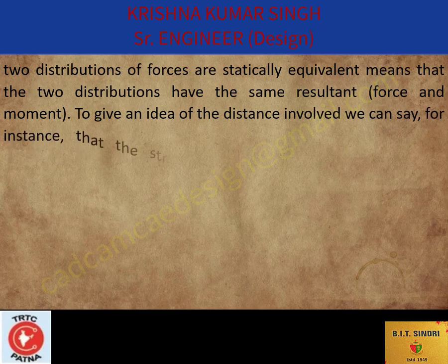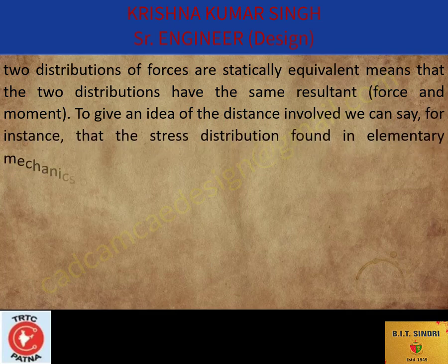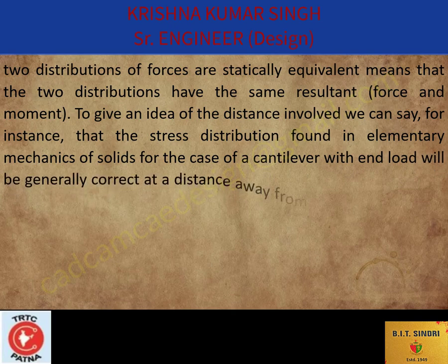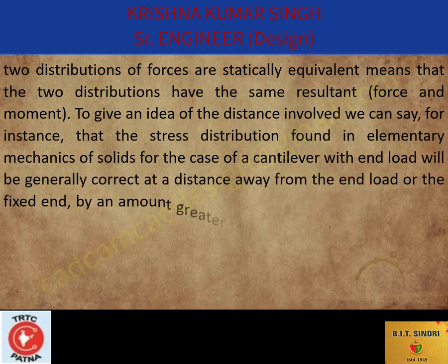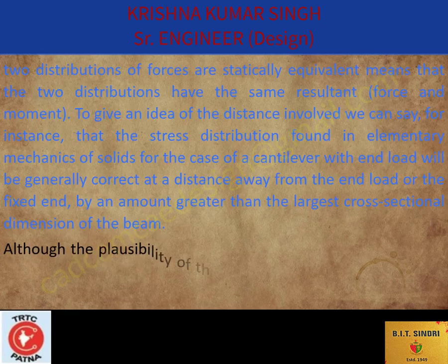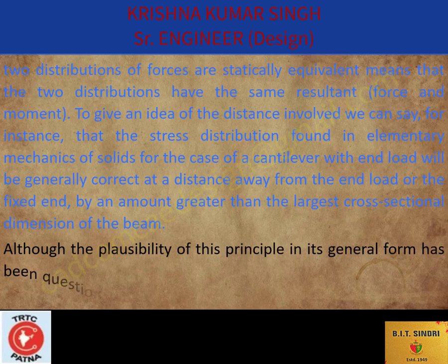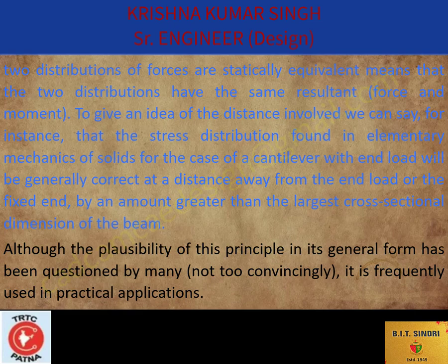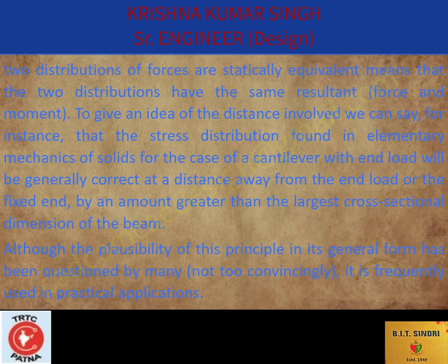meaning that the two distributions have the same resultant force and moment. To give an idea of the distance involved, we can say, for instance, that the stress distributions found in elementary mechanics of solids for the case of a cantilever with end load will be generally correct at a distance away from the end load or the fixed end by an amount greater than the largest cross-section dimension of the beam. Although the validity of the principle in its general form has been questioned by many, it is frequently used in practical application.